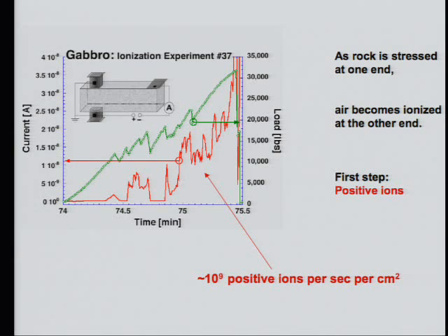rock surface. And here we use pistons, and we add some teeth to them by gluing some hardened steel bearings at the bottom of the piston, so that the stress is very, very concentrated and bites into the rock in order to produce really high degrees of mechanical deformation without breaking the rock immediately. And that is what you see here.